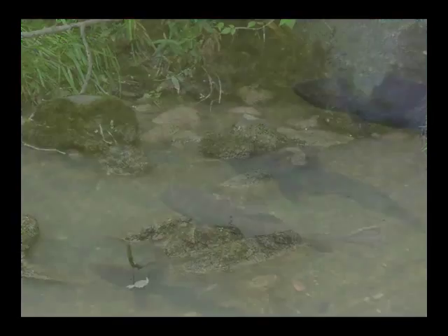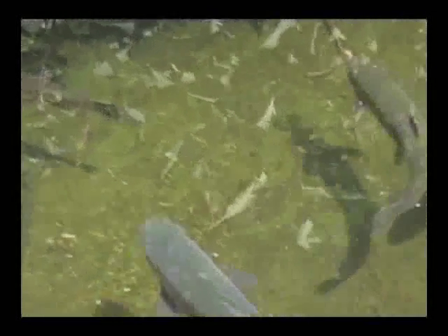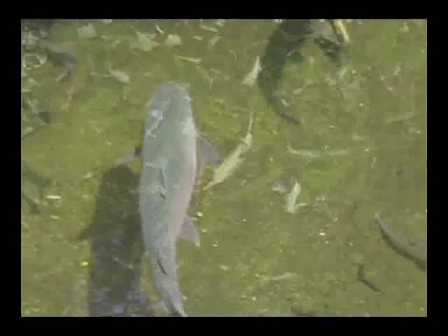food source for fish. Suspended particles may adhere to gill structures of fish and aquatic insects, inhibiting the transfer of oxygen. The suspended sediment can lodge in feeding and other breathing structures of aquatic plants and animals, causing starvation or suffocation. The deposition of sediment also affects stream shape, causing the stream to become wider and shallower. A wider, shallower stream is more prone to temperature extremes, which can force cold or cool water fish species to relocate in order to survive.